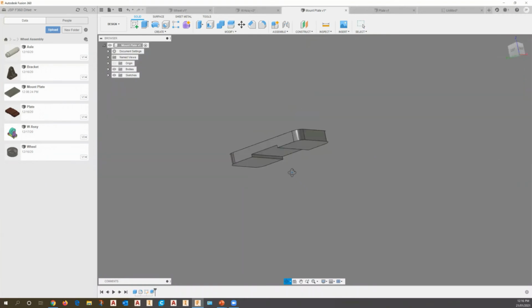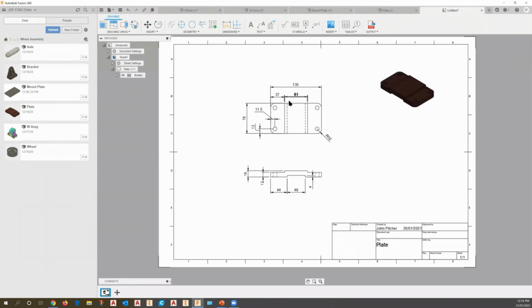All right, what we're going to do next is very similar on the top, only we're going to draw another rectangle and do a cut down here. So the size of the other rectangle on the top face is, again, a 4 millimeter step down, but it's 61 millimeters wide, 37 in from the end.